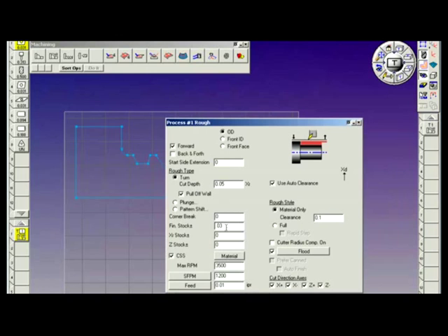This would probably chip the insert or maybe even knock the part off center. Uniform stock is fine when doing straight work without shoulders or radial features with angles. But in a situation like we have here, I prefer to use XR stock of 30 thousandths and Z stock of only 5 thousandths. This way, when I perform my finishing operation, I'll only be taking 5 thousandths off the faces in Z. CSS will stay in effect.